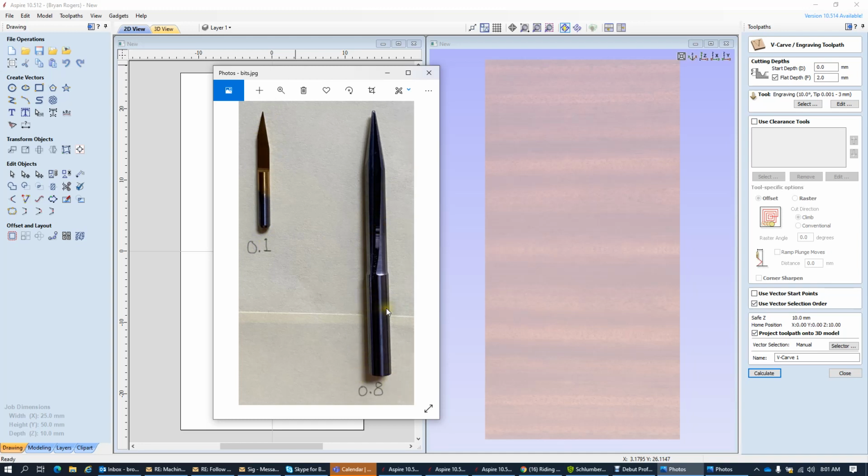This is a 6 millimeter shank, which is roughly 1/4 of an inch, and it's 0.8 millimeters flat on the top. Now, as you see, it's not really 0.8 flat. What that is, is a 0.8 radius on the end. You can see it's a ball end. So it's a 0.8 radius, which is right at 1.5 millimeters wide. So that means that it's a 30/1000ths radius at the end of that, which makes a fairly big cut, but you can still actually use this pretty good.